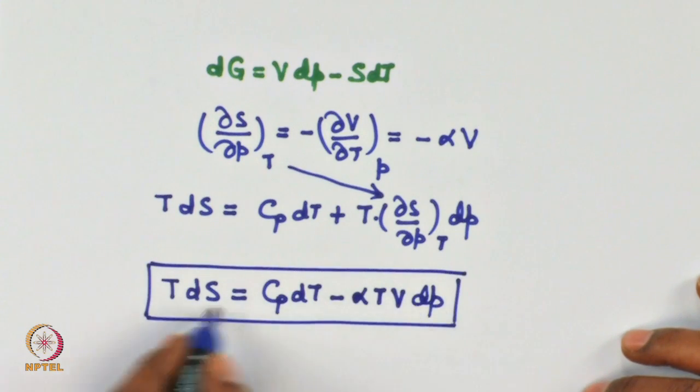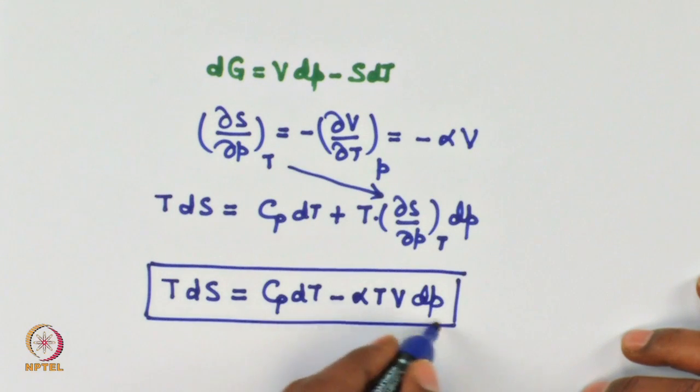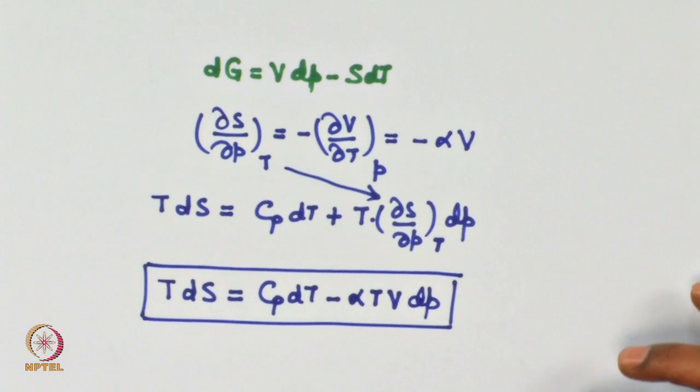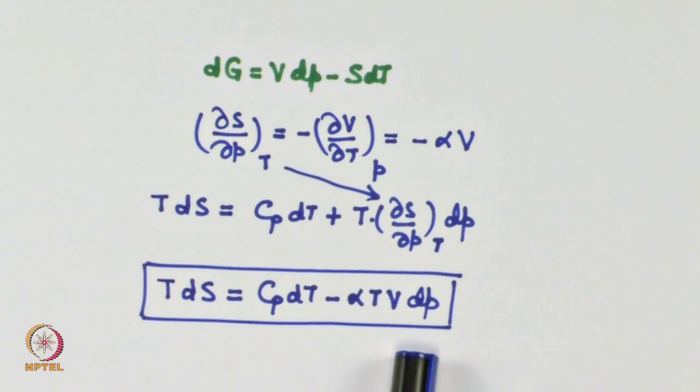Now, you can integrate and calculate the changes in entropy when the other properties of the system are known. So, this kind of equations allow us to account for the deviations from ideality. Please remember again that in deriving these equations, we have not assumed any ideal behavior. For example, this particular equation will allow you to calculate the entropy changes when the temperature changes and pressure changes.